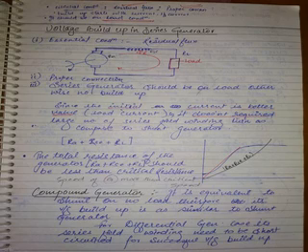So 8 volts means there is some residual flux in the poles, due to which you have 8 volts. If you observe, in all the three cases, open 8 volts means what is there in the machine? Residual flux. Residual flux is producing 8 volts and it has been completely erased away, so the voltage became 0. Why did this voltage become 0? What could be the reason? Only one reason, that is 3 only. No other reason. Yes or no?